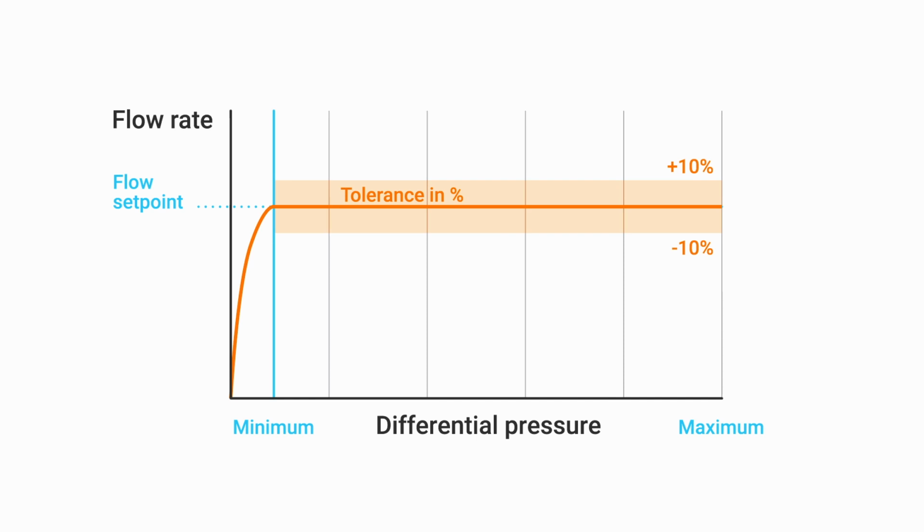That's over the whole range of the valve, so much better than pressure-dependent control valves, but can pose an issue if you're trying to commission between 100 and 110% of design flows. Also, the spring that forms part of the pressure regulator has different flow performance on rising pressure and lowering pressure. This phenomenon is a type of hysteresis, and it has caused problems getting repeatable flow readings in the past.